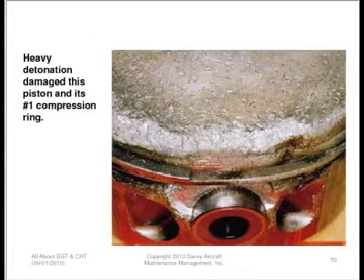Here's an example of a piston that was damaged by heavy detonation. You can see a lot of pitting on the piston crown. You can see corner melting. Sorry, I don't have my little pointer on, but pitting on the piston crown, corner melting on the piston. It actually melted to the point where the top compression ring was compromised. Obviously, this caused significant damage to the engine, and probably got quite a lot of metal in the engine, so this is undoubtedly a tear-down situation.